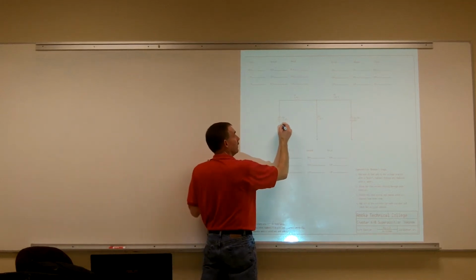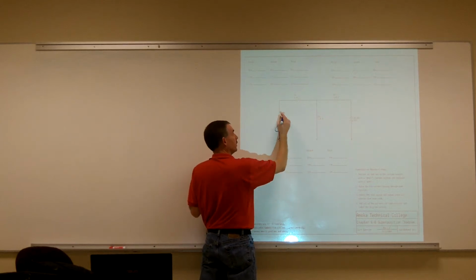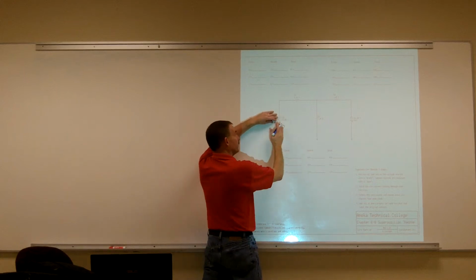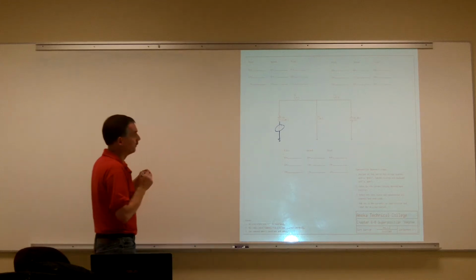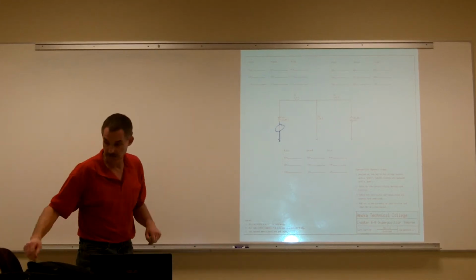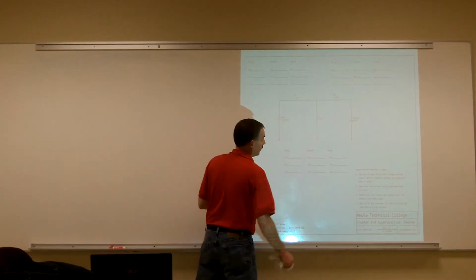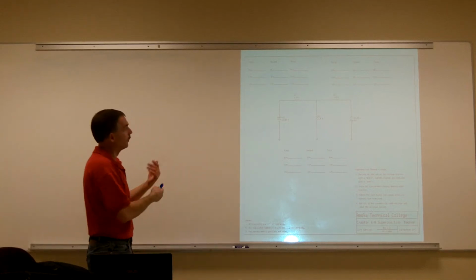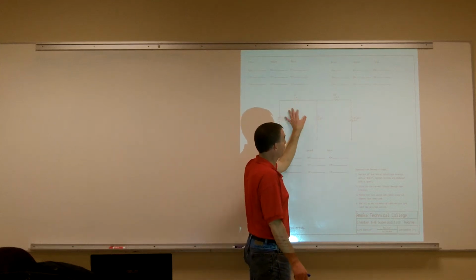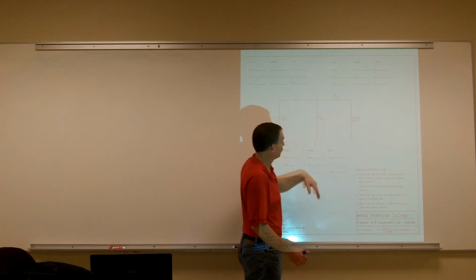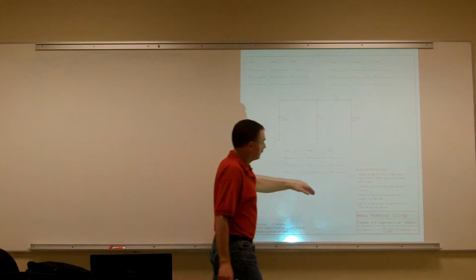For example, if I had a superimposed AC signal right in series with this power supply, it would ignore that this power supply is even there. That AC signal would go through, and it would look at the circuit differently than what the DC one would. And we see that when we get into solid-state devices. So when we get into solid-state devices, I'll bring up superposition again. That's what we're really taking a look at: how do I analyze a circuit that has both an AC and DC circuit. Here we can just do it with our DC sources and it acts the same way.